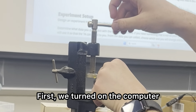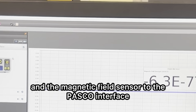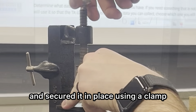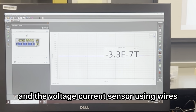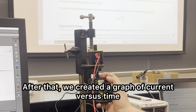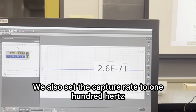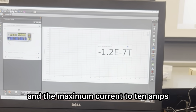Now, let's walk through the process step by step. First, we turned on the computer, opened the Capstone program, and connected both the voltage current sensor and the magnetic field sensor to the Pasco interface. Next, we set up a 200-turn coil and secured it in place using a clamp. Then, we connected it to the power supply and the voltage current sensor using wires. After that, we created a graph of current versus time, where current is on the y-axis and time the x-axis. We also set the capture rate to 100 Hz and the maximum current to 10 amps.